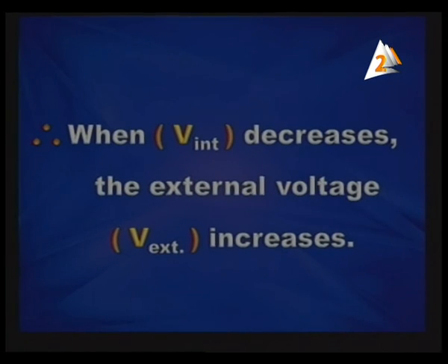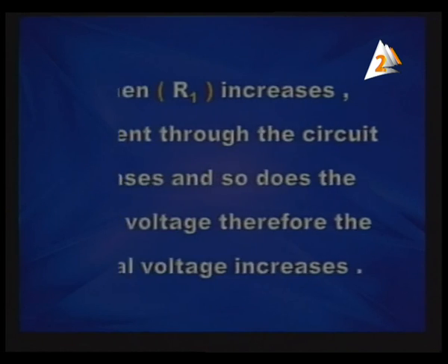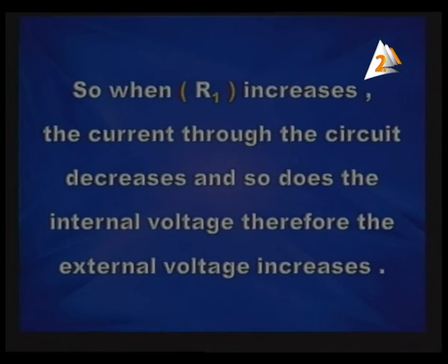Still something we want you to answer. V2, what about V2? It is the voltage across R2. What about it? Before we answer this, let's sum it up. When R1 increases, current decreases, and so does the internal voltage, therefore external voltage increases.